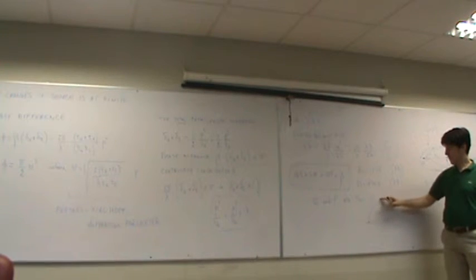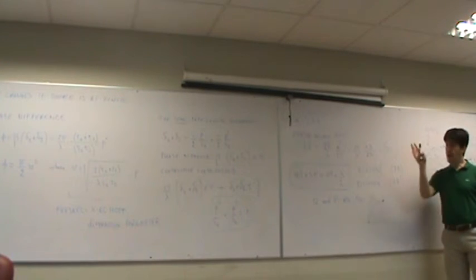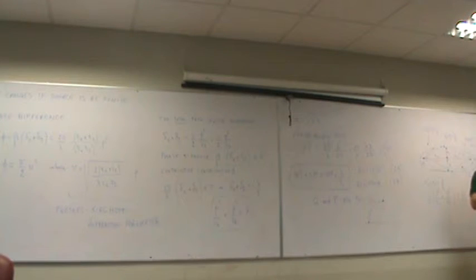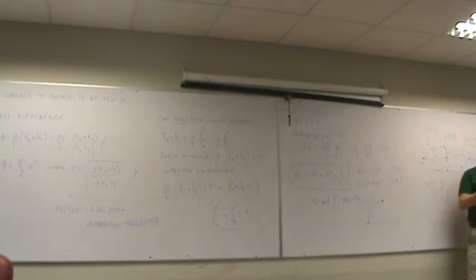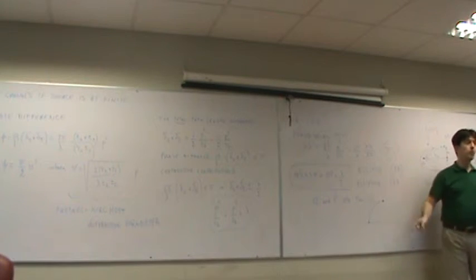You cannot take for granted that the electric field inside the building is weaker than what is outside. On average, this is true. But you can have some focusing effect in certain points. And if you have more than one window, for example, a periodic series of windows, all those effects can accumulate. And you can have some hot spots inside your environment where you can have an electric field that is substantially stronger than what you have outside.